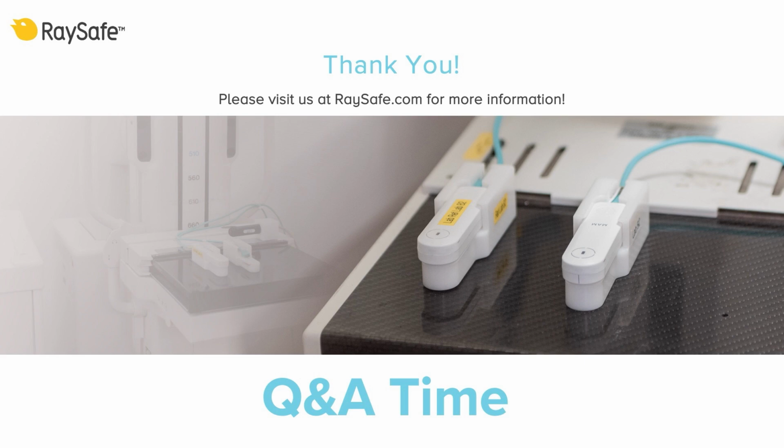Can the 452 measure high dose rates? Yes, the 452 has a very wide dynamic range. So it can measure all the way from background up to 1 sievert or 1 gray an hour, which is 140 Röntgen per hour. And the wide dynamic range is thanks to the combination of the GM pancake and the solid state sensors in the design of the 452.